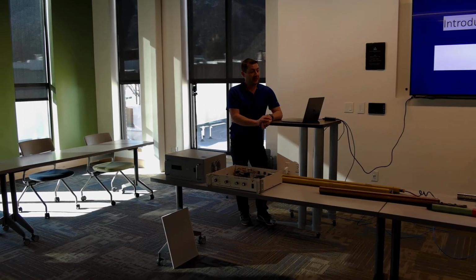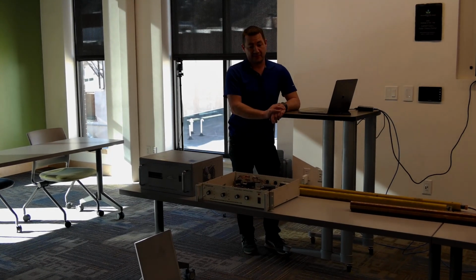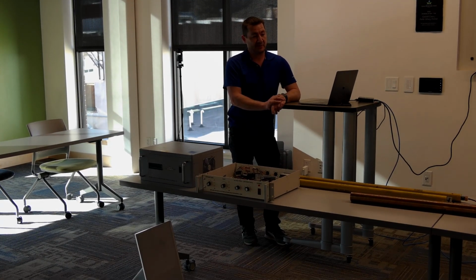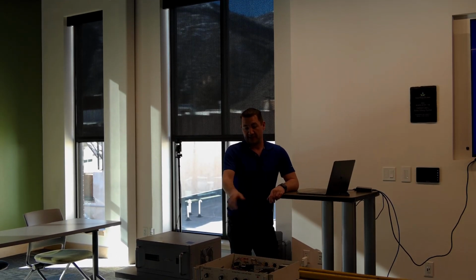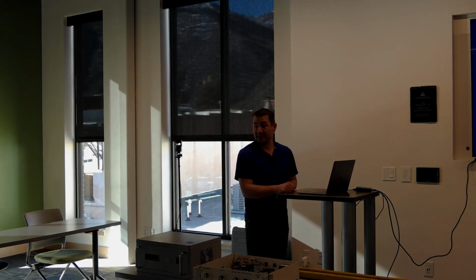So the tool that I use is a downhole surveying tool that transmits live data to the surface through these boxes here, and we decode that signal on surface and it gives us our inclination, azimuth, gamma, pressure, and a bunch of other things. So I'll give you an introduction and then I'll go through everything specifically and give you a little more detail of what everything does.